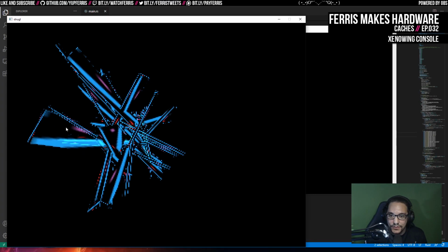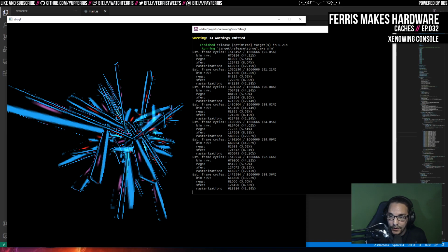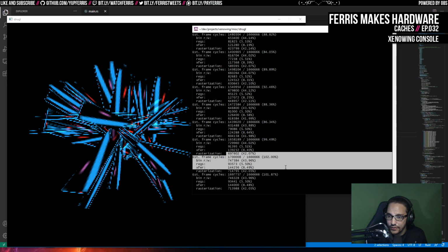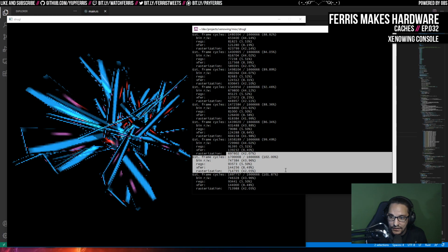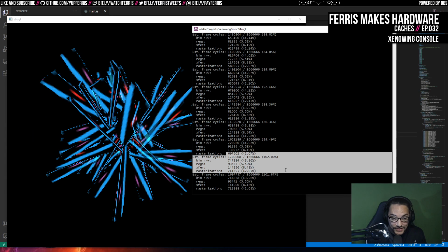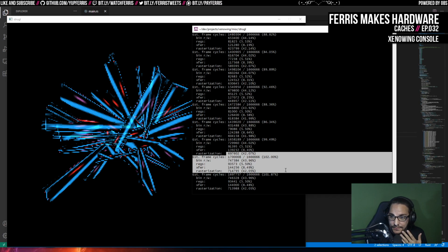So again, this is the actual simulated RTL for the rasterizer. It runs a bit slower, which is why I have both. And you can see here, there are frames where we actually blow the 60 FPS budget. And this is on the order of hundreds of triangles. This is not good. And this is just rasterization. Again, this does not include geometry transformation.